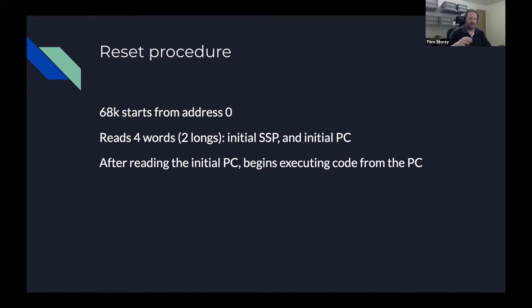As I said before, we need to turn a blind eye to the fact that this didn't actually execute straight out of a reset, but there's two ways that a CPU would start executing code. On reset, the program counter gets initialized to some default value, and then the processor starts looking at that address for the first instruction it wants to execute. For example, a Z80 would reset the program counter to 0, and at address 0 it would expect to find the first instruction that it can start executing.